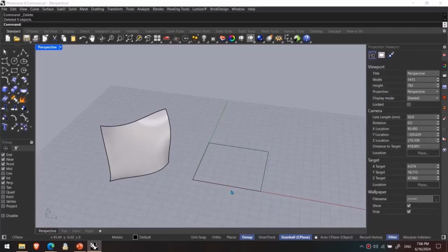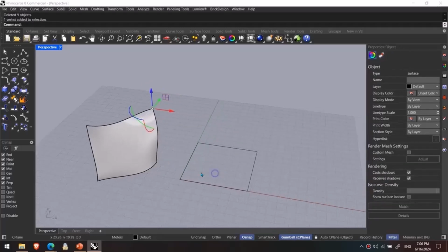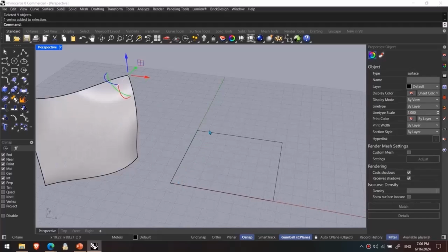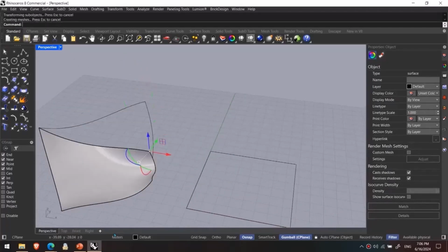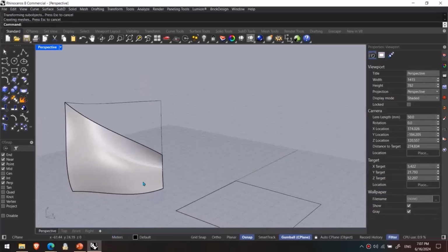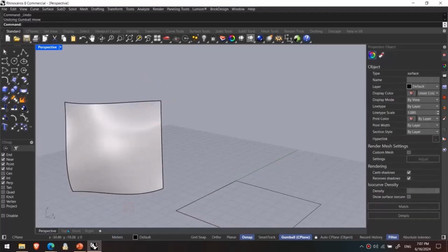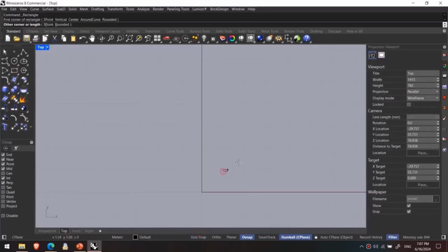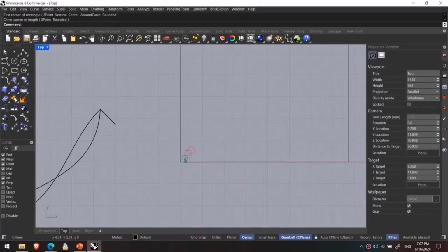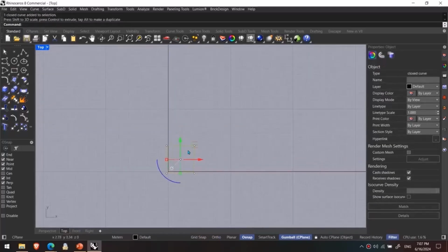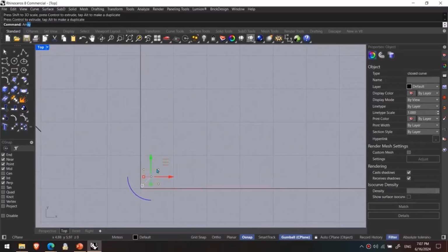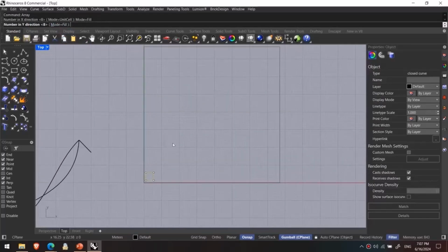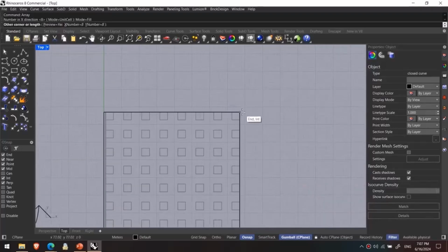great. In the continuation, I want to have a pattern where the circles are being minimized after one another. Let's see. Without editing the surface, since I don't want to revise the surface. Firstly, let me draw some circles here, or skewers. Watch this. I select the skewer, then I resize it, select it, and then I want to start array. I set it to fill 8, 8 and 1.